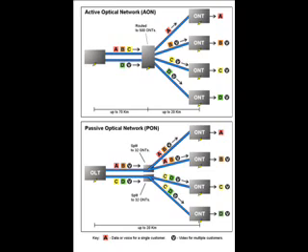Passive optical networks do not use electrically powered components to split the signal. Instead, the signal is distributed using beam splitters. Each splitter typically splits a fiber into 16, 32, or 64 fibers, depending on the manufacturer. A beam splitter cannot provide any switching or buffering capabilities. The resulting connection is called a point-to-multipoint link. For such a connection, the optical network terminals on the customer end must perform some special function.